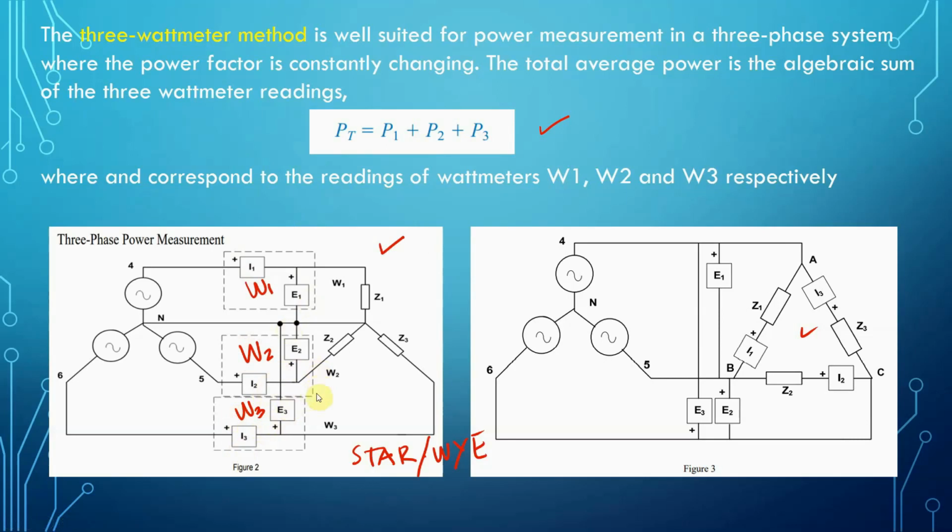When you connect your ammeter and your voltmeter, make sure that for this phase here, you are connecting I1 and E1 properly. You cannot measure I1 and measure this voltage here using E2. No, the software will be confused. Of course, it will just give you a value, but the software will be confused. We have to follow I1, E1, I2, E2, I3, E3. And we did it already in the previous experiments, the Y connected load, and here also, we did it already in the delta connected load.